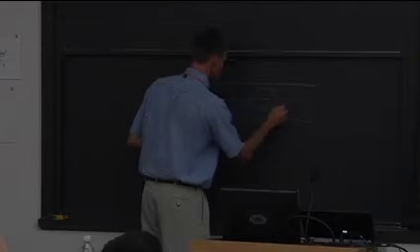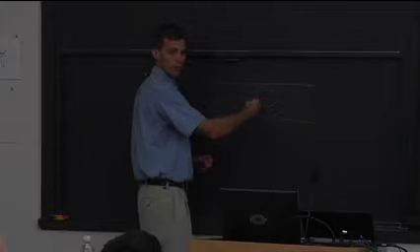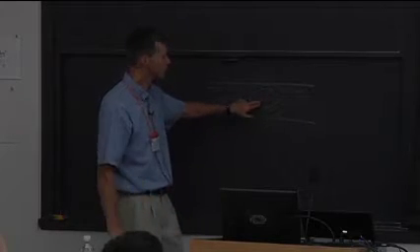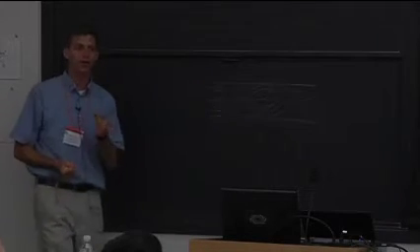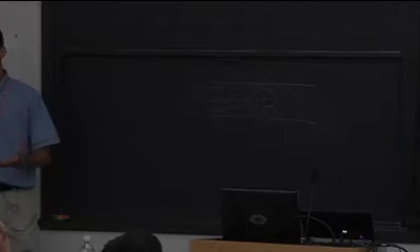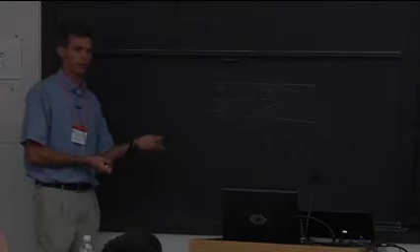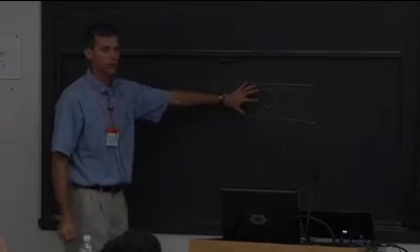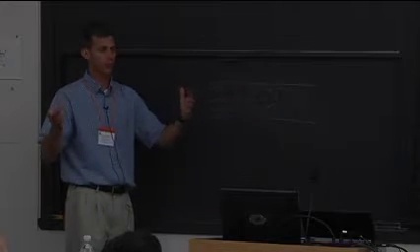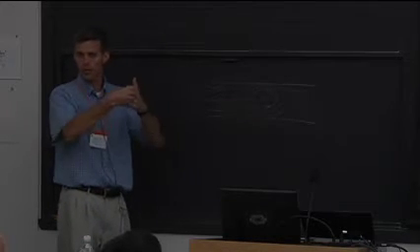And so then what happens is the flow goes around it. It physically looks like somebody just stuck a ball into the middle of the flow. And this is called vortex breakdown. It's a natural hydrodynamic instability of swirling flows. This is why combustors like to have swirl flows, because you can get natural flow recirculation without any type of flow, you don't have to stick metal into the flow to make flow separation. Well, it turns out that,